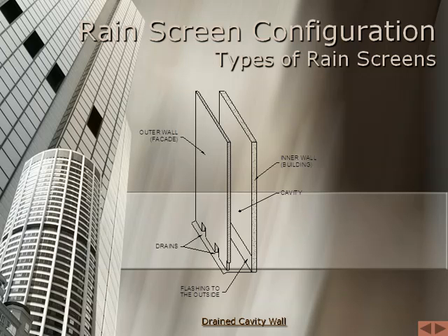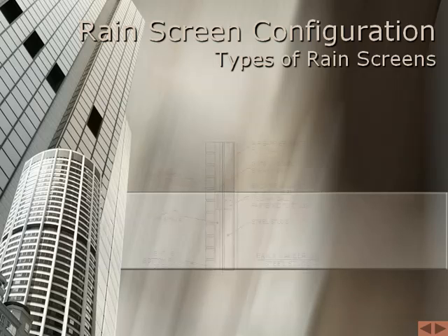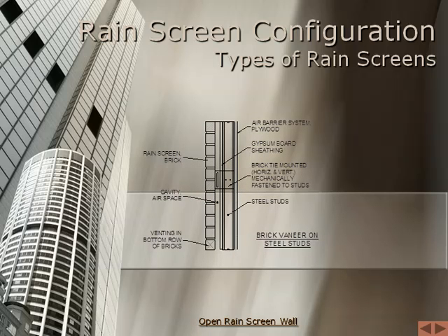Penetrating water may exceed the volume that the building wall can drain internally, or it may be retained in the building wall and cause deterioration of materials. The open or simple rainscreen wall differs from the drained cavity wall with the placement of the air barrier. Most modern cavity walls and walls clad with siding act as an open rainscreen.